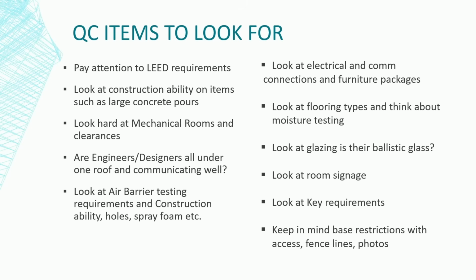Look at flooring types and think about moisture test. Sometimes moisture testing is a requirement in the RFP and the specs, and sometimes it's not. If you're doing a lot of poured slabs, over time that moisture is going to wick out of the concrete. If you don't do the moisture test and you lay down flooring too soon, that moisture is going to make glue stop holding. It's going to make your floors buckle. Then you're ripping up floors, you're shot peening, your drying time. When you're at that point of a project where you're laying down the flooring, losing schedule is like losing gold. So please pay attention to the moisture test. Talk to your design firms, talk to your flooring folks, figure out what kind of moisture testing you need to do.